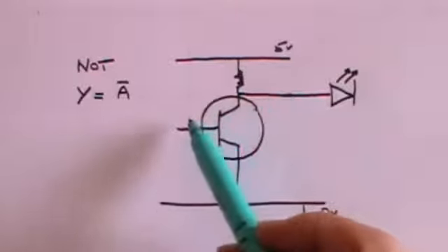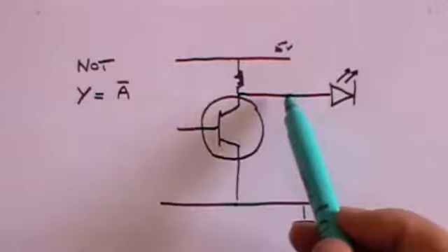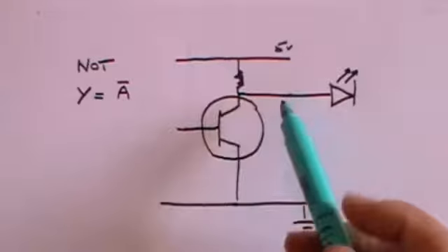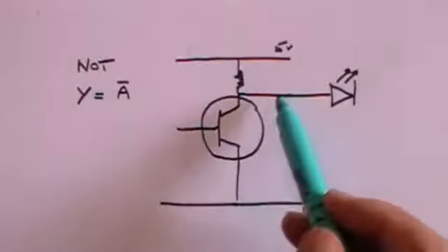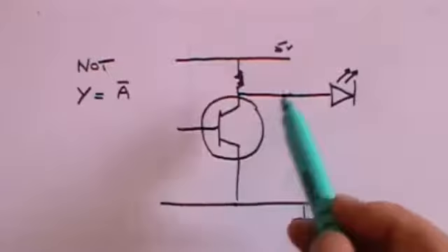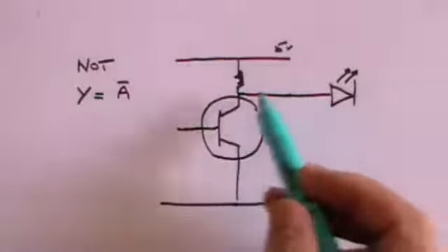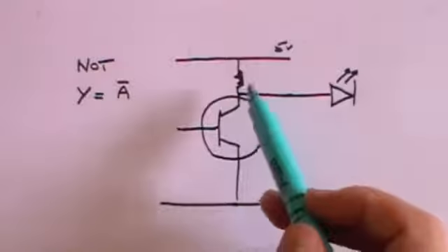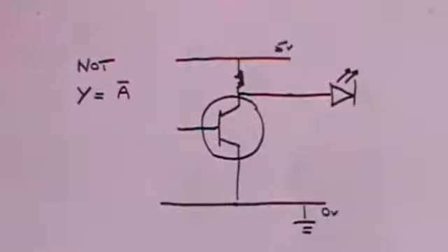And so you've now got a positive voltage on the base, the input, but no voltage on the output, because a current is flowing through here, and so essentially this and this are at the same potential, and that potential is 0. And so the whole 5 volts is dropped across the resistance here. So this is simply an inverter.